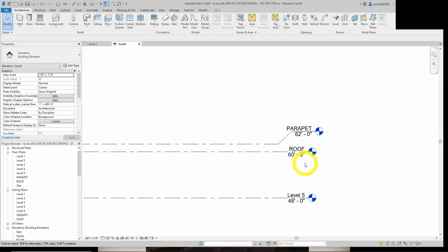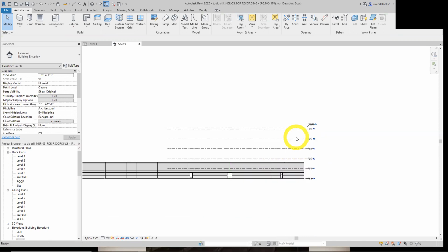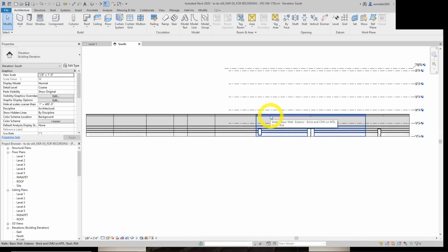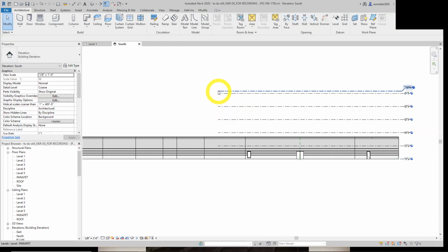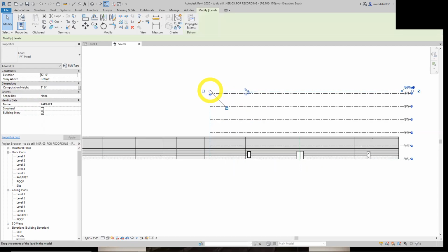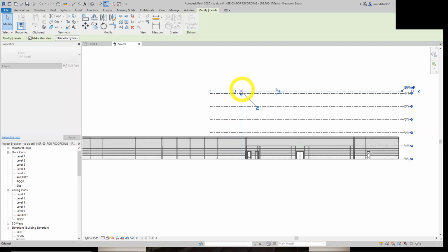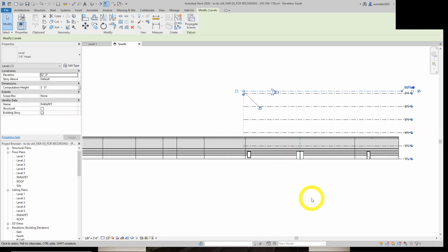And making other adjustments into page 119. Let's see what they ask there. We're going to select the parapet level. Let's see where they want to drag it on the picture on page 119. So we're going to get it kind of close to here. Let me get that one lined up. If you just saw what I did there, it lined them up automatically. Here, actually, since we're grabbing them all at once, bring them right about here, our levels, close to the corridor